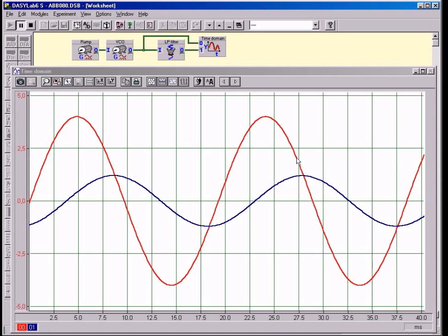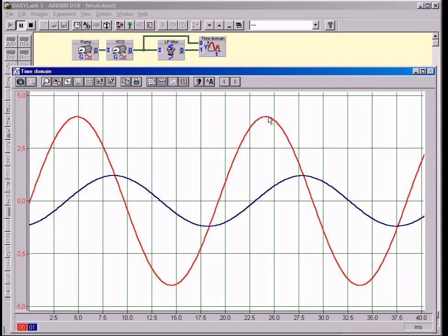By means of a function generator and oscilloscope, it is possible, using time-consuming measurement procedures, recording the measurement values, and calculating by means of a pocket calculator, to determine the representation of the frequency response according to amplitude and phase between the input and output voltages. For complete and careful measurement with evaluation, you need roughly 2 hours.